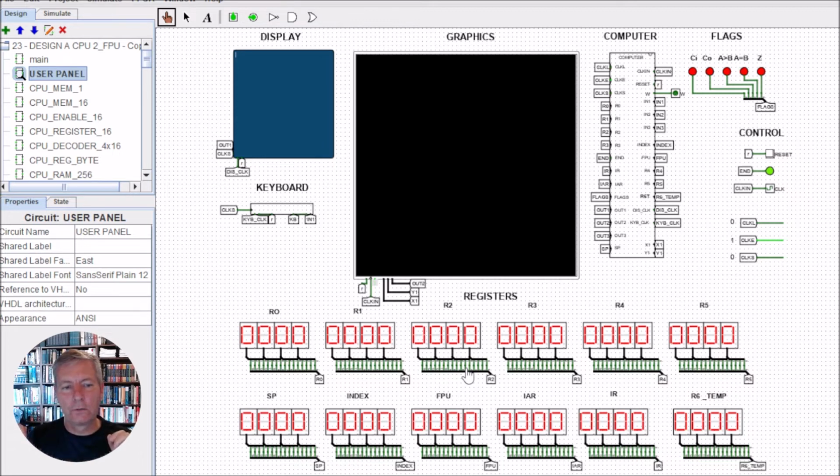But obviously I want to show you the Excel spreadsheet that I used in order to generate the different parts of the program that we need. For example, we need to load up the microcoded ROM with the correct start positions, and we need the compression ROM with the correct start positions, and the microcoded ROM with the correct values for our sets and enables for each of the functions. So I'll open that up now and show you, but it's also in the resources section, so you can open it up too. It's the Excel spreadsheet, so let's have a look at that now.